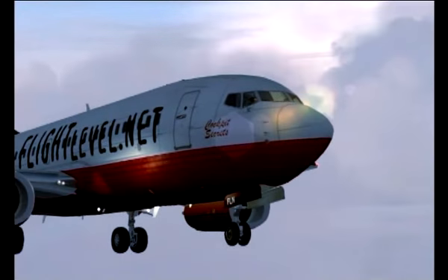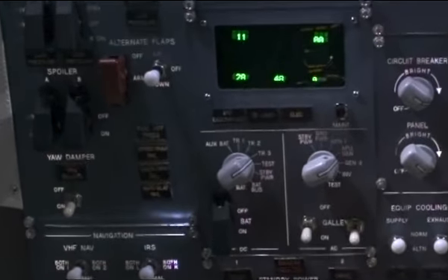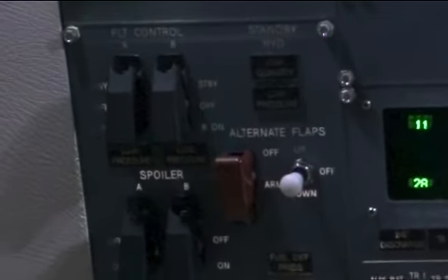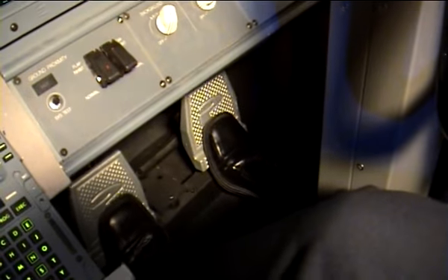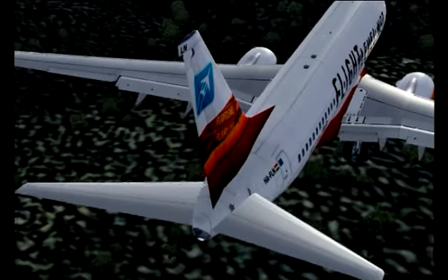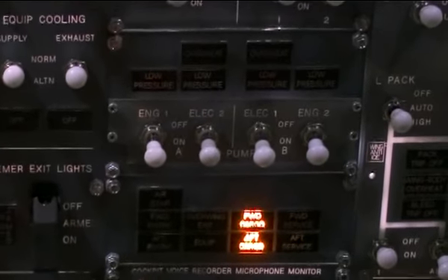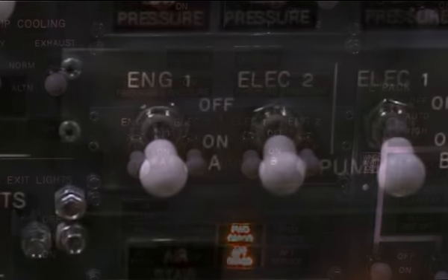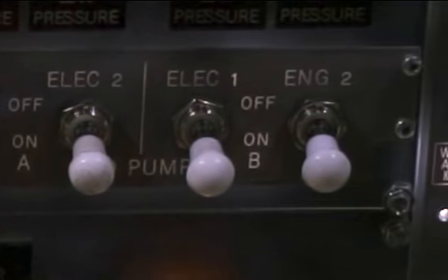For safety considerations, the aircraft has 3 independent hydraulic systems called A, B, and standby, a backup system to operate the rudder. Hydraulic systems A and B each have 2 independent pumps to provide hydraulic pressure. One of the pumps is engine-driven, the other is electric.